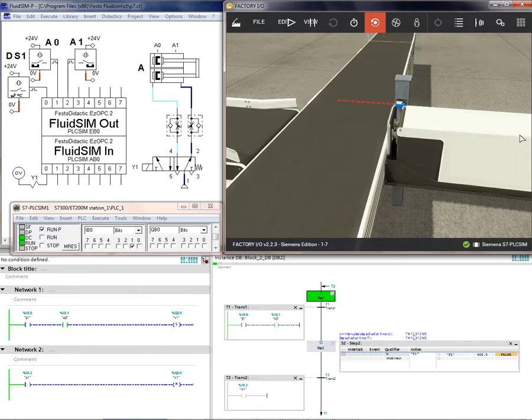For example, I can describe it in this Factory I/O, but imagine this is A, the position of A0, where this sensor is mounted and installed, and as you can see this is activated. And the question is why? Because in the normal situation Y equals A minus, and A0 is activated.